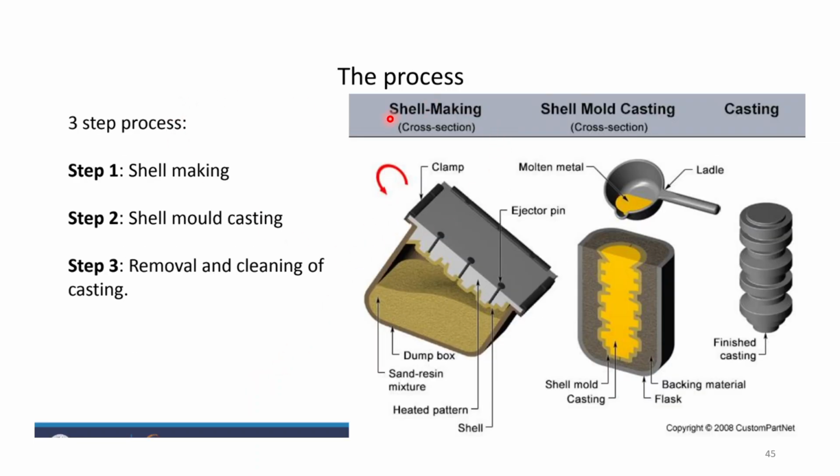So this is the process. There are only 3 steps. First you have to make the shell, then shell mold casting, then removal and cleaning of the casting. For this you require various tools: drop box, sand resin mixture, the heated pattern, and the shell.